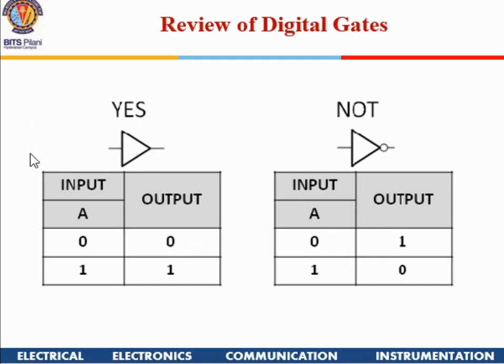Say you have an input gate wherein a function is realized with a complex set of gates, but that may not have the current carrying capacity. Whereas you can design a buffer which can transmit that input signal without loading the previous stage.